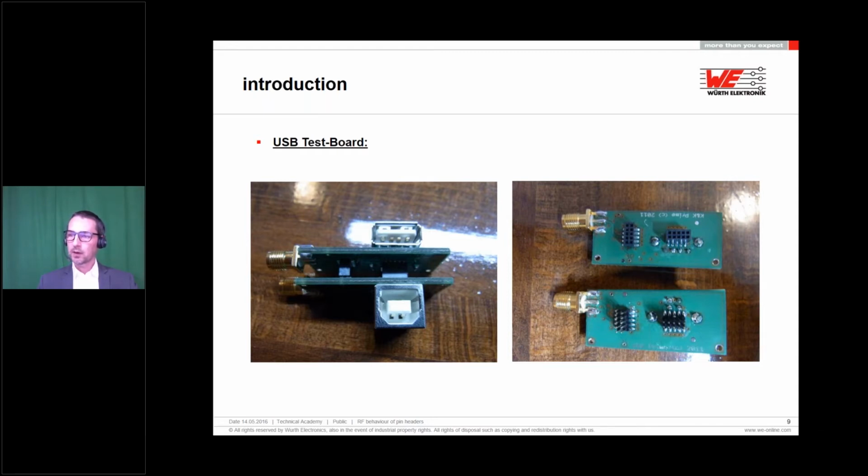On the other side, you have these coaxial connectors on the board, also with a board-to-board connection with the pin header. So if you have your individual single-ended signal, you could try it out to see if it works. This was quite nice to have locally with the customer to test it. But when the ADM or the FAE goes out, we still could not provide real data. So we have been thinking about how to do that.